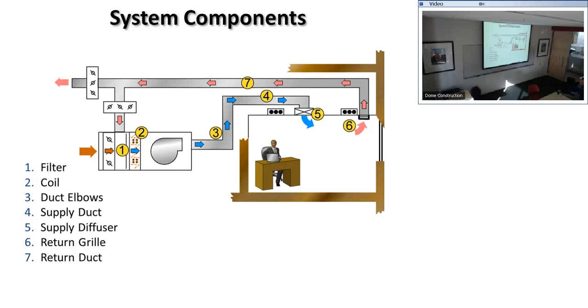You also can't use the plenum for clean rooms, correct? It has to be a ducted system. Oh, a clean room, yeah, it'd be a whole different game. But for labs, you usually want to control pressure. The labs we won't, because we don't know what's coming out of the lab. You don't want to put that across your whole ceiling.